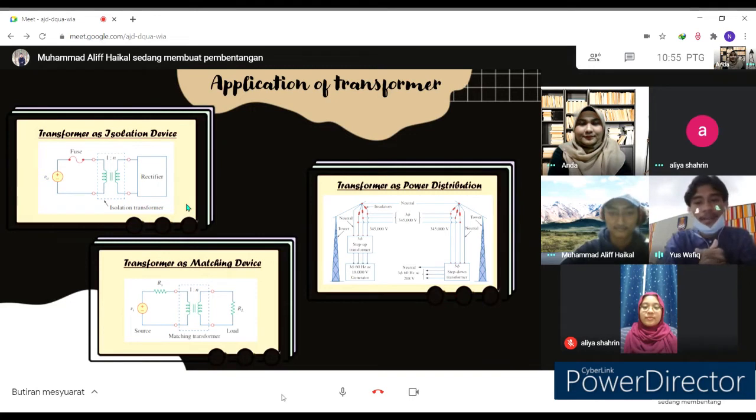Next, the transformer as a matching device, or we can call it impedance matching. Impedance matching makes sure that the output impedance of one stage, called the source, is equal to the input impedance of the following stage, called the load. This match allows for maximum power transfer and minimal loss. This maximum power transfer occurs when the output impedance of the source is equal to the input impedance of the load, because if the output impedance is bigger than the load, more power is lost in the source.